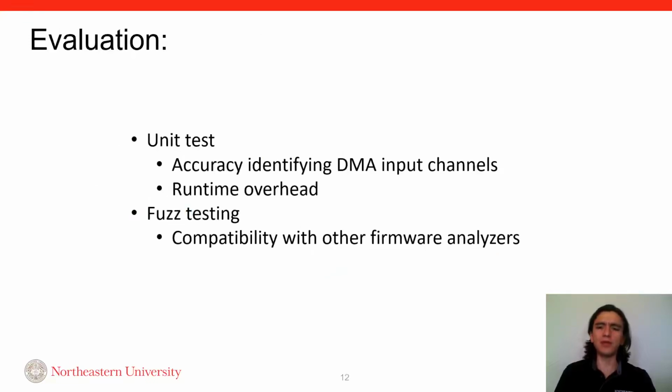We evaluated DICE using unit tests for two purposes. First, to verify accuracy in identifying DMA input channels, and second, to measure DICE runtime overhead. We also perform fuzz testing campaigns to confirm that DICE supports fuzz testing on real-world firmware, and found bugs that existing firmware analyzers cannot identify.